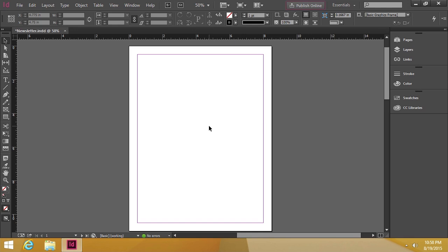You can also change the origin point of rulers. Right now, the origin point is in the upper left-hand corner. See, there's 0 right there and 0 right there. You can change that. I'll go ahead and click on this upper left-hand corner of the ruler and drag, and notice how there's a crosshair. And I'll drag over to this edge and release. And now we've changed the origin 0, 0 to right there and there. I'll just reset that. So I'll click and drag this back there, because that's typically where you want 0 and 0 to be.